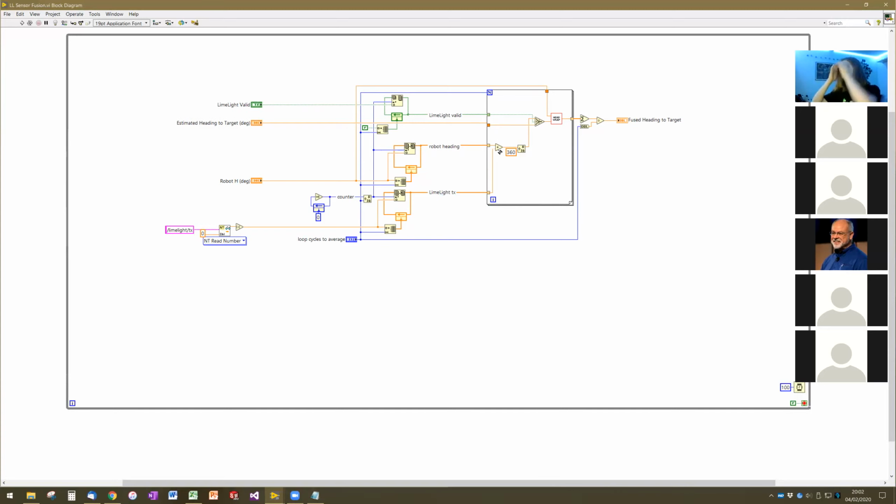So with this addition and this modulus calculation, we're putting this angular estimate from the LimeLight in the same reference frame, in the same units, as the angular estimate from the estimated target heading. Does this combination of the LimeLight angle with the robot heading to get the absolute angle make sense to people? We do that in a couple other places in the code, but it's also here.